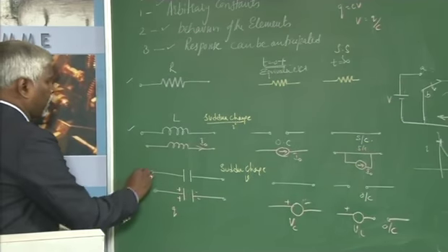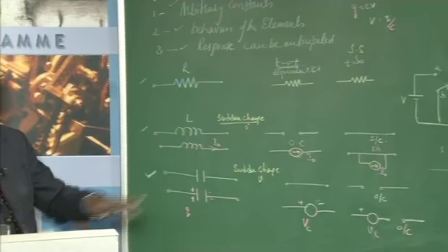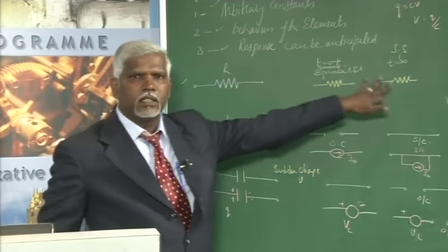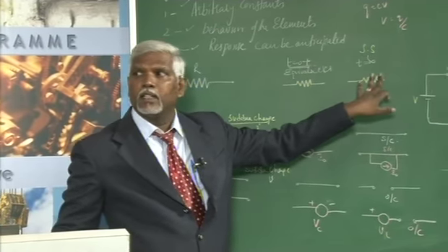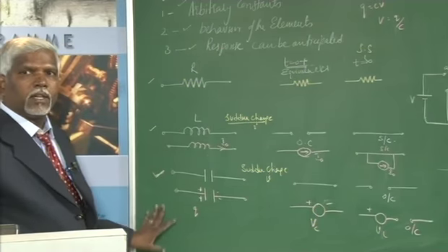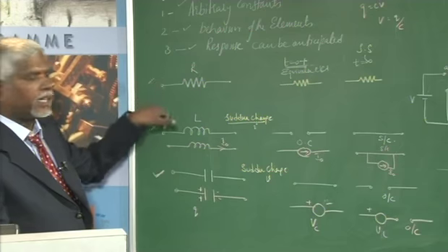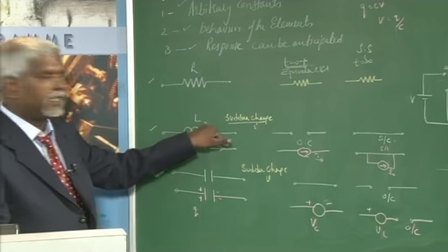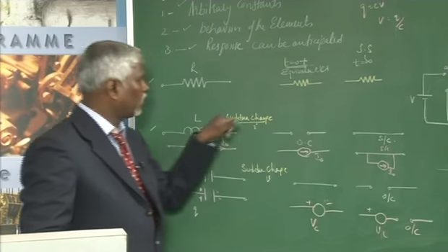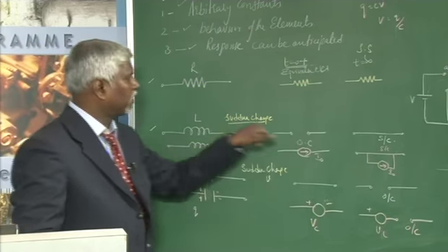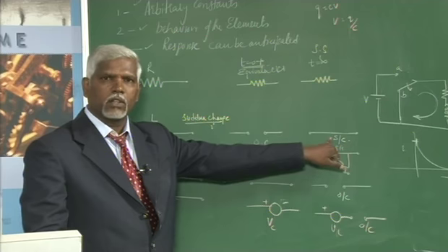These three elements and their behavior should be in your mind. I reiterate again and again: if you understand this table, the next few problems we do in initial conditions become very simple. Inductor does not allow any sudden change. If there is no current, there will be no current even immediately after switching; it gradually allows current and finally acts as a short circuit.